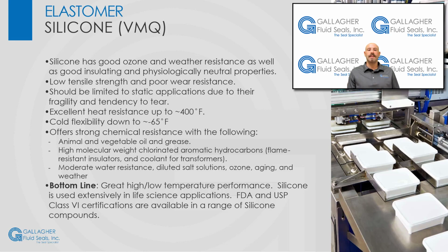Silicone has excellent heat resistance up to approximately 400 degrees Fahrenheit, with special compounds up to 500 degrees Fahrenheit, and cold flexibility down to approximately minus 65 degrees Fahrenheit, with special compounds down to minus 175 degrees Fahrenheit.